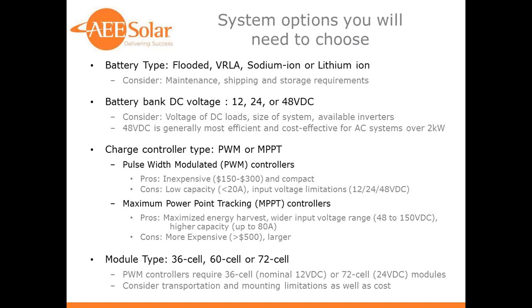There's a variety of different charge controllers available. Pulse width modulation or maximum power point tracking are two different styles of charge control. They are used for different applications with different types of PV modules. So it's really important to look at that and choose the right thing there. There are many pros and cons to each one. MPPT controllers are generally more expensive, but they also do a much better job at harvesting energy from solar panels, so you can typically get more charge off the same number of modules.